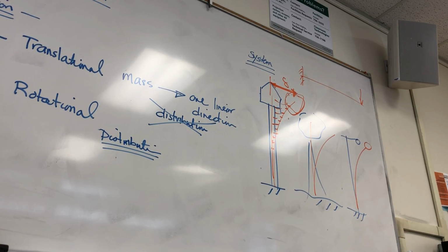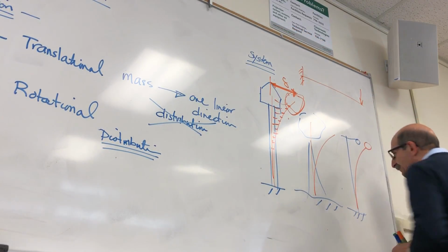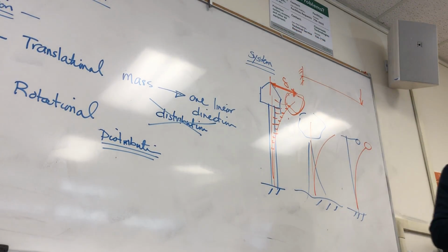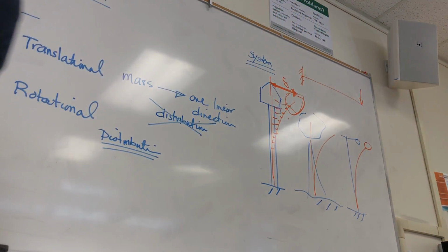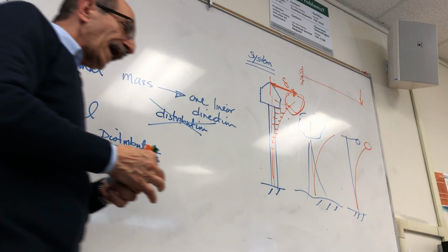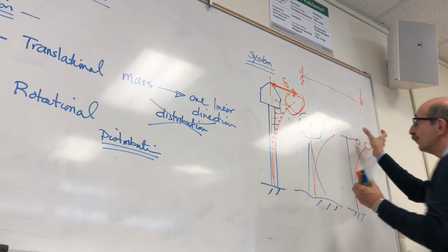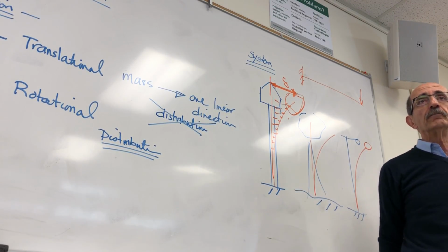So a single degree of freedom means assuming that the entire structure can be represented by its total mass. You know how that total mass moves. Overall, you have an understanding of how that moves. And the movement that this goes through, we call that the degree of freedom.